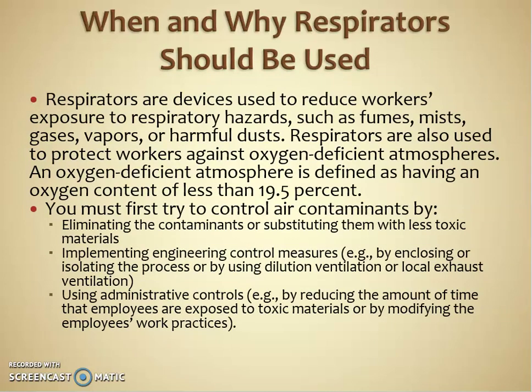Now let's talk about the respirators. When and why respirators should be used. Respirators are devices used to reduce workers' exposure to respiratory hazards such as fumes, mist, gases, vapors, and harmful dust. Respirators are also used to protect workers against oxygen-deficient atmospheres. An oxygen-deficient atmosphere is defined as having an oxygen content of less than 19.5%.